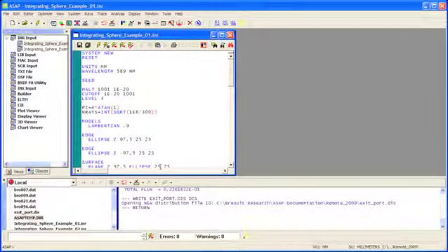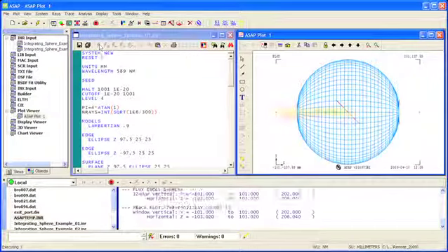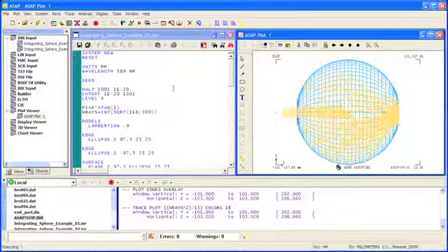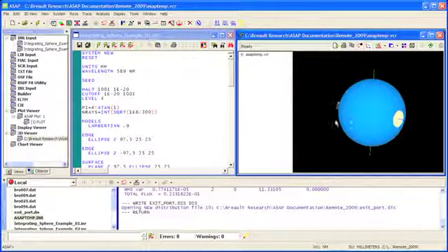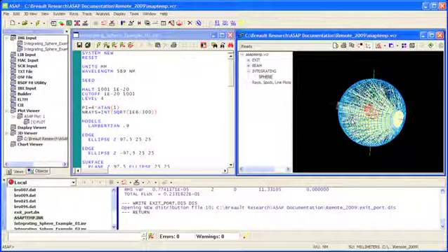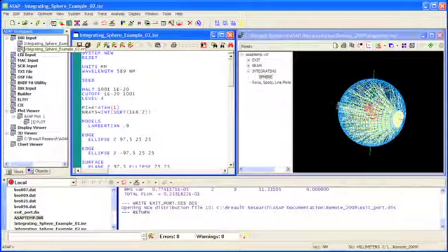We'll run a simple example of an integrating sphere and trace a few thousand rays to calculate its overall efficiency. We can see the geometry and rays tracing in our 2D and 3D viewers. Now let's use the power of remote in ASAP to perform real Monte Carlo simulation using the same example. We'll change the script shown to trace approximately 20 million rays and distribute the computation across multiple ASAP remote sessions.